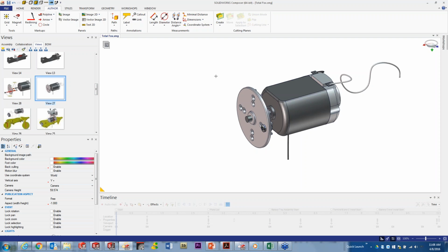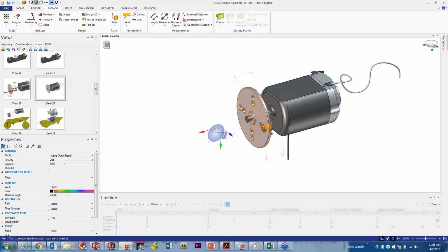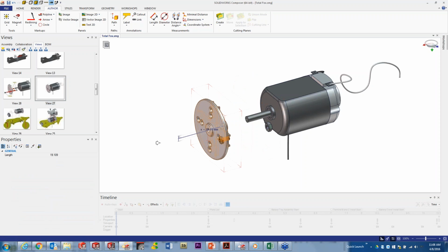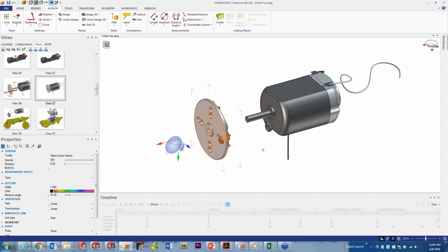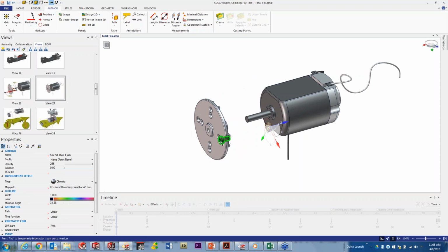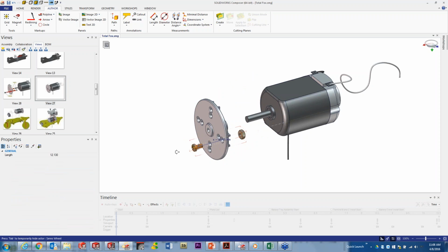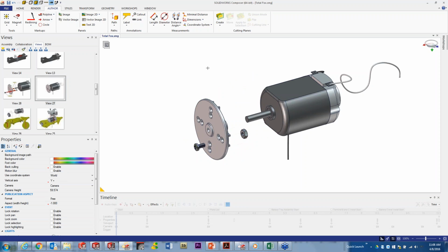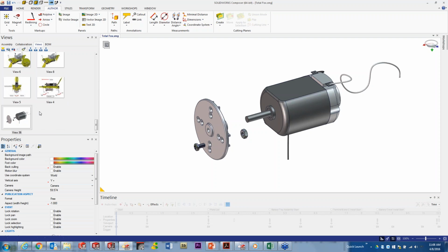So creating data is a very simple capture operation. In many cases, it's a matter of grabbing geometry on the screen and doing simple things like translate and rotate. You can pull parts and push them into different positions, and this is a lot like capturing configurations in SolidWorks. However, there's no need for those excessive additions to your file size, which is what configurations do there. And it's also very simple just to capture things, and it grabs whatever is in the frame. What's hidden, what's shown, what position these files happen to be in.